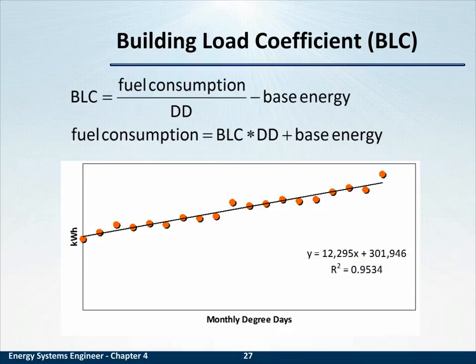And if you plot your fuel consumption by degree days and interpolate that with a straight line, the slope of that line is your building load coefficient, and the y-intercept of that line is your base energy. And this is a valuable exercise to see the performance of your building envelope.